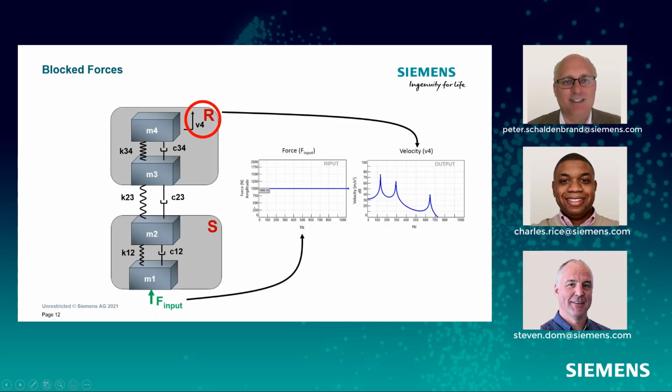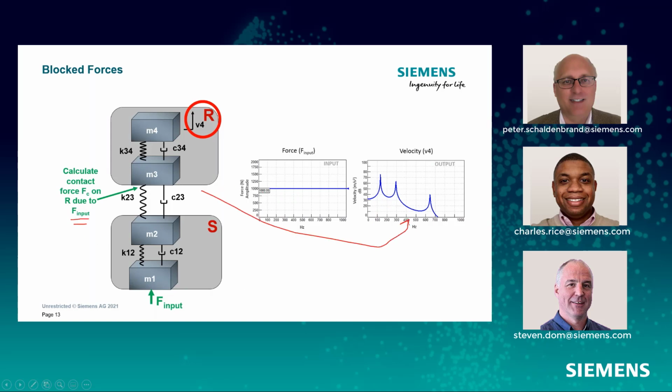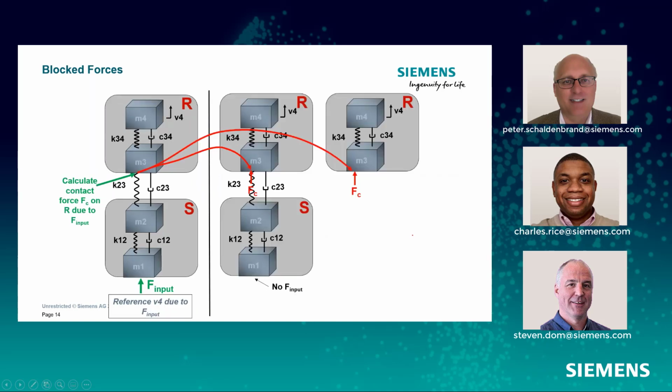We can take an empirical example like this, with masses and stiffnesses, and play around with it. That way we don't have to think about a real thing. There can be multiple attachments, etc. But we have a force input, something like this, and I can get the response output. So all I need to do is calculate a force over here that gives me this same response output.